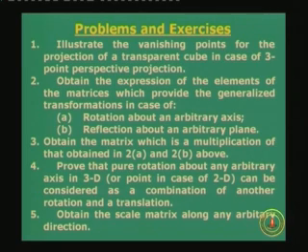perspective transformation. Now, do it for scaling, because we have got the scaling matrices for special cases along x, y or z or all together. So, given along a particular arbitrary direction, what should be a scale matrix? Please try to solve all these problems as given here and also the problems which I have talked of earlier. It will give you a lot of confidence both in terms of vector algebra, matrix algebra and transformation matrices in both 2D and 3D transformations.